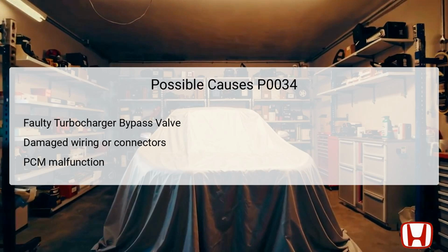Furthermore, issues within the PCM itself cannot be ruled out. If the PCM malfunctions, it may send incorrect signals or be unable to read the valve state, thus triggering DTC P0034. Each of these elements must be evaluated during the troubleshooting process.